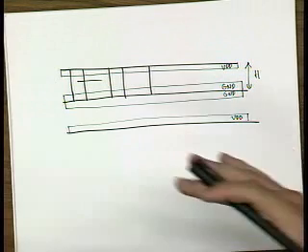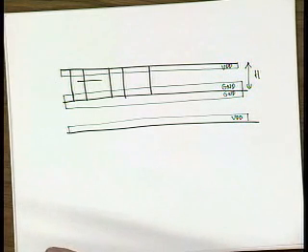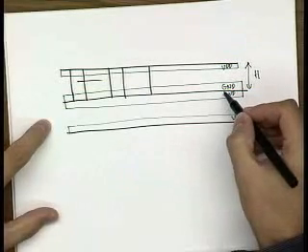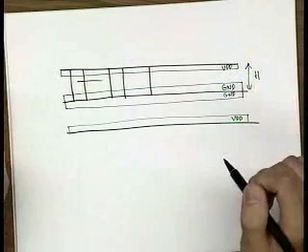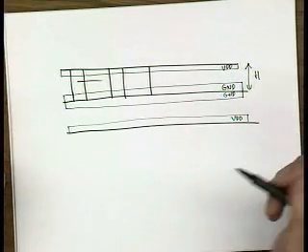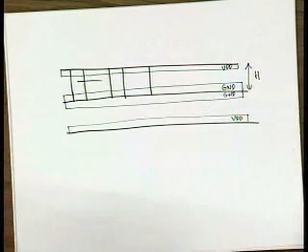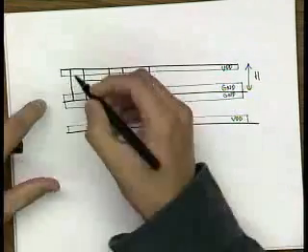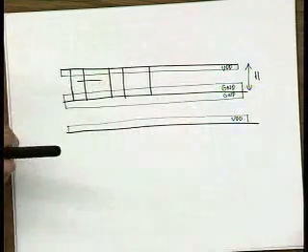You can abut cells next to each other without even a need to connect these ground and VDD, as you will see in an illustration in a second. The cells are already pre-made in such a way that you just put them next to each other. VDDs and grounds are all connected. You have nice density, and let's go back to slides for a second.